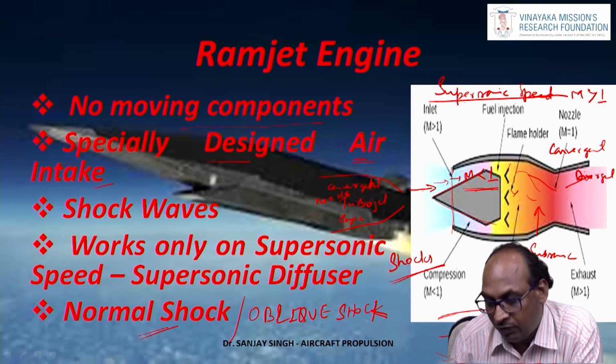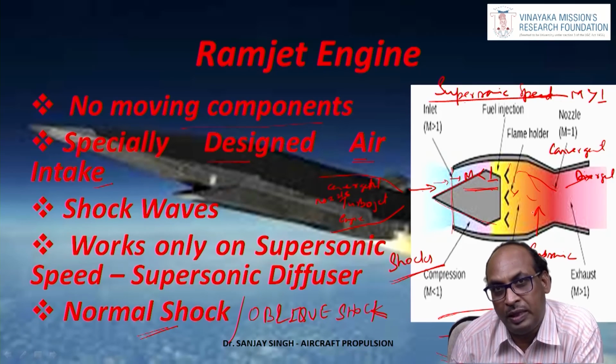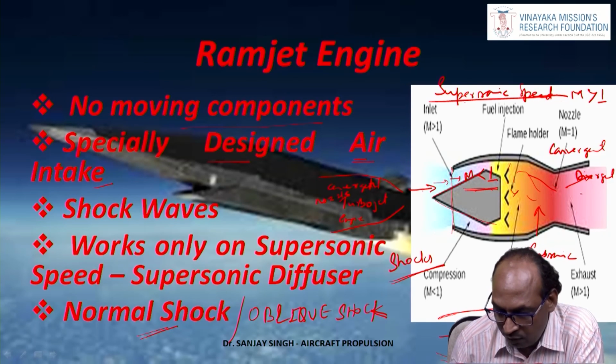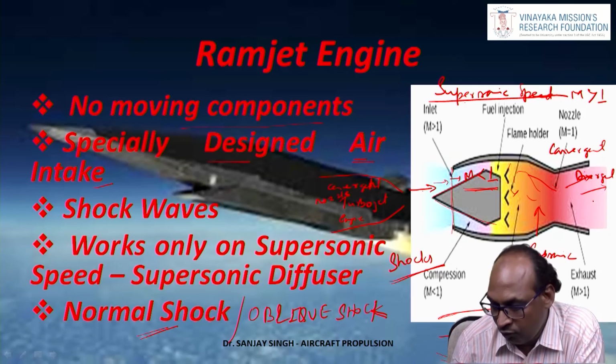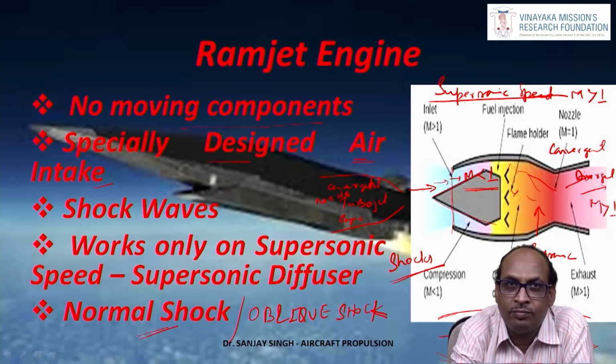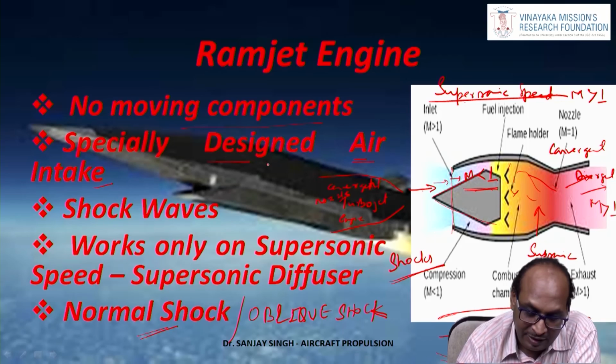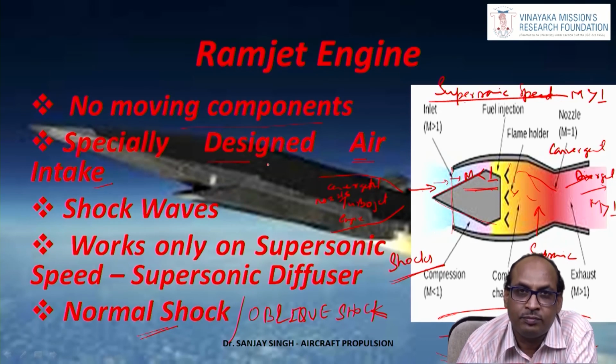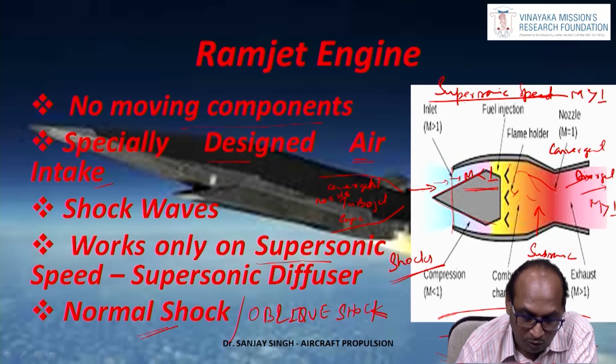And then the convergent divergent nozzle. The aircraft or the engine which is traveling at supersonic speeds uses a convergent divergent nozzle. With the help of this nozzle, we will be able to have a Mach number more than 1, which means supersonic speed can be generated. In this ramjet engine, combustion is taking place at subsonic speed. As I told, it is working only at supersonic speed.